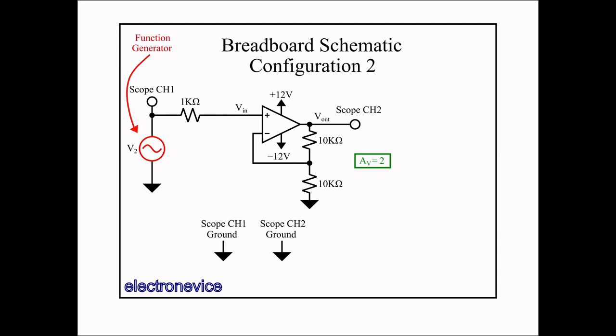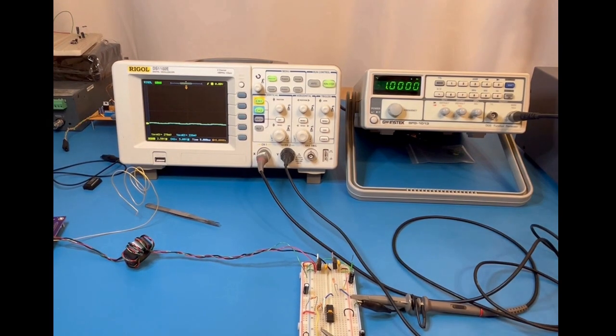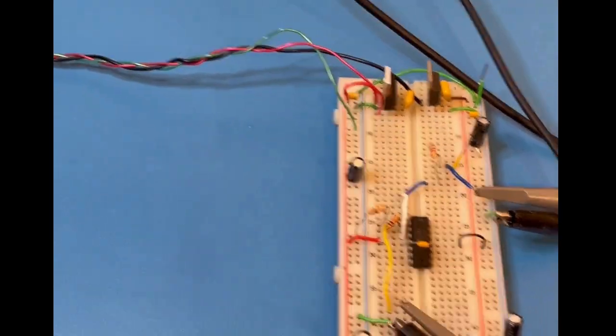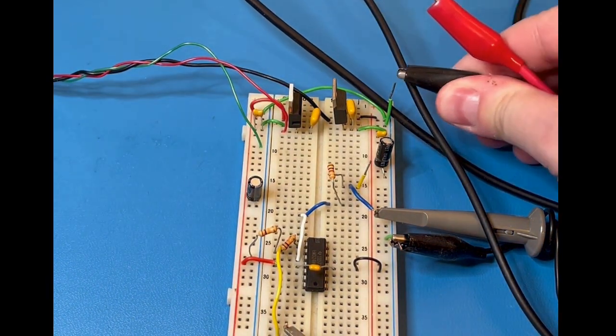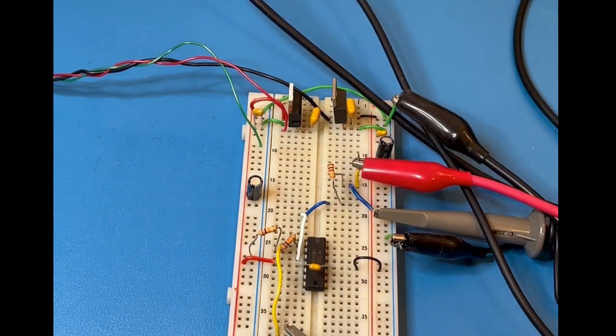So we're moving along to another circuit with a function generator instead of a DC voltage source. It has all the same features as the previous circuit. Function generator as the voltage source, scope channel 1 on the function generator, along with the scope grounds, and everything else is the same. Here, we are connecting the function generator to the input of our op-amp circuit now, instead of that power supply voltage source. But we're connecting it to this same spot with the channel 1 and channel 2 scope probes in the exact same spot that they were before, and everything else the same.